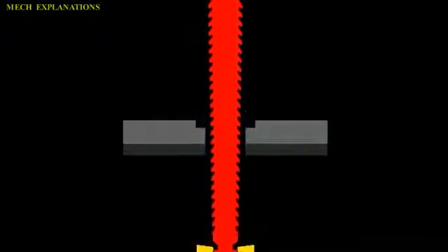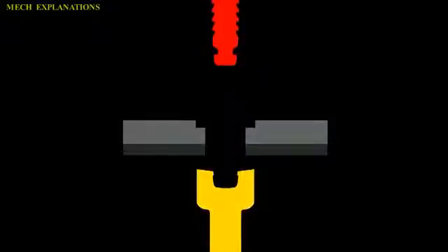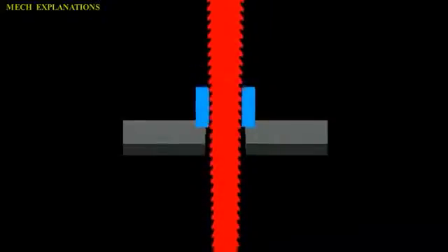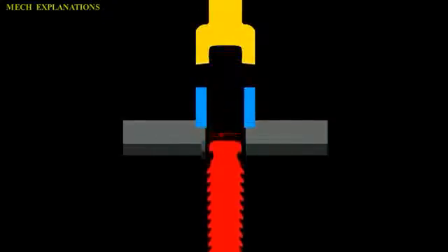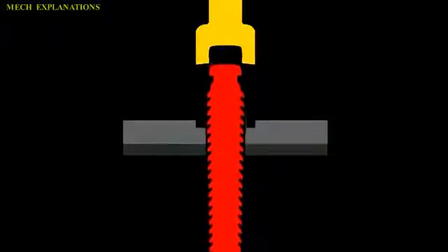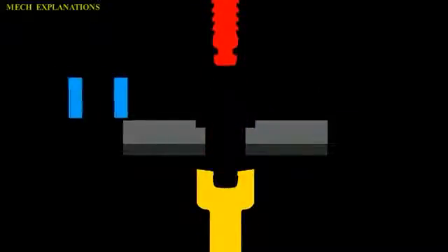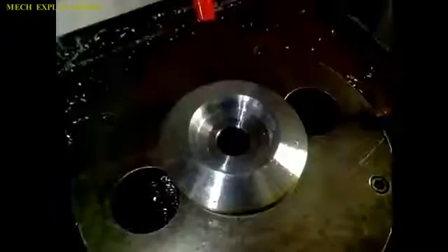In linear broaching, which is the more common process, the broach is run linearly against the surface of the workpiece to effect the cut. Linear broaches are used in a broaching machine, which is also sometimes shortened to broach. In rotary broaching, the broach is rotated and pressed into the workpiece to cut an axisymmetric shape. A rotary broach is used in a lathe or screw machine.